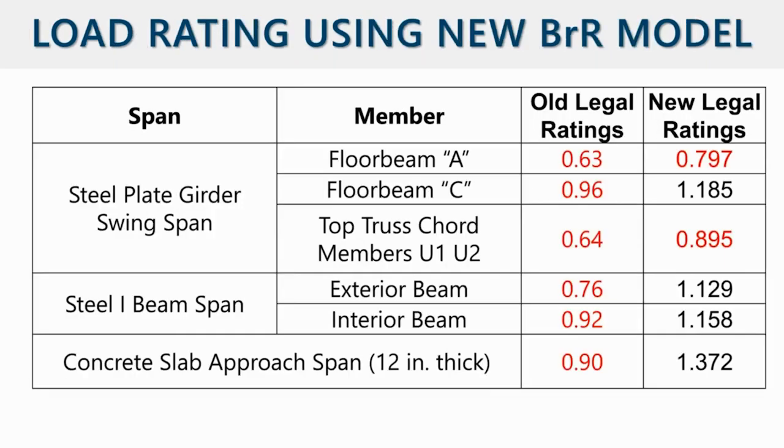So after we did everything, this is the comparison of the rating before and after the load test, where we applied all these changes to the new bridge rating model. You can see here all the load ratings were improved, especially the floor beams, intermediate floor beams, also the approach steel I-beam spans and approach slab spans. Right now they all have load rating factors above 1.